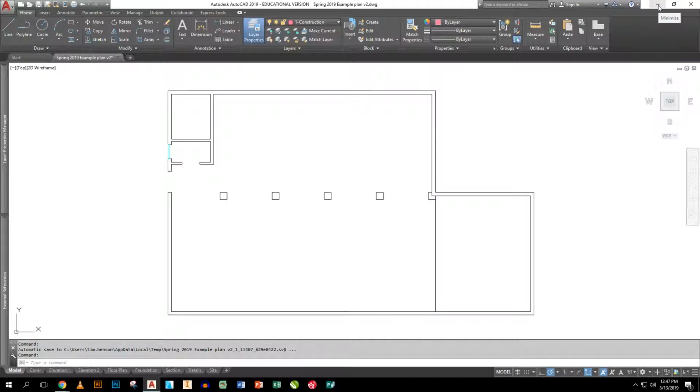Now, on a floor plan, we only show horizontal dimensions. We do not know how far up windows are. We do not know their vertical heights. We will put builder's notations on them, or a window or door symbol for a building schedule, but we don't show where the height of the window is. We only show what its dimensions are. So right now, we're just going to throw in the windows and doors.